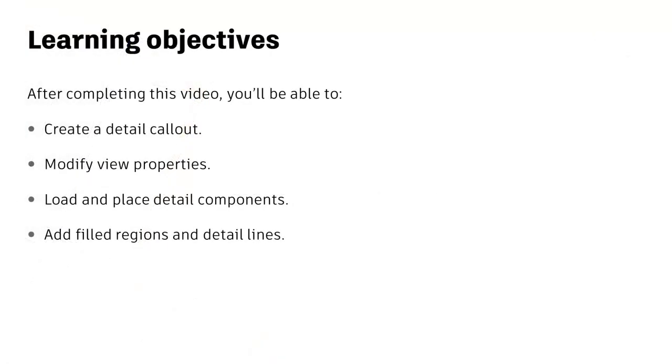In this video, you'll learn how to create a detailed callout view from a larger section view. You'll see how to modify the view properties to prepare it for detailing, and you'll learn how to load and place detail components, add filled regions and detail lines to complete the detail.